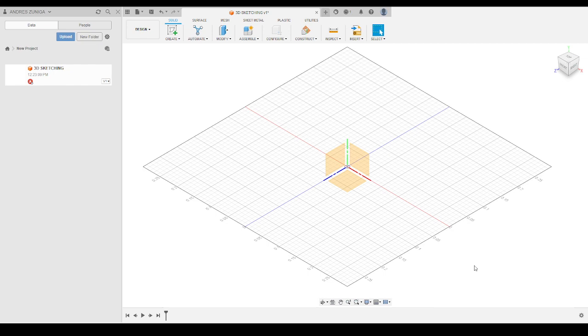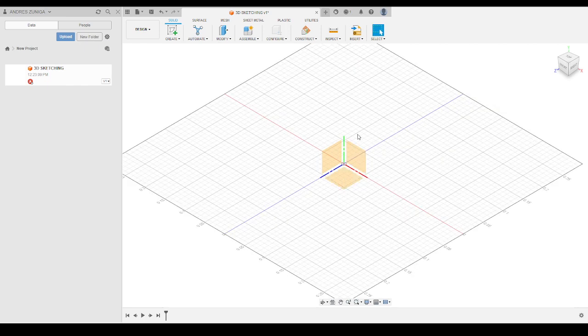Now, this chair is just going to have a tube that goes all around. So I'm going to, first of all, make sure that I have my units correctly. So I'm going to click on units on the document settings and then go to meters because I want to make my chair kind of like the real scale. Okay, I'm going to press OK. And I'm going to click on create sketch.